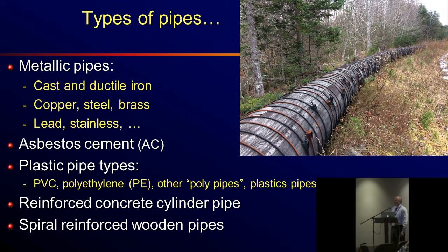Asbestos cement, there's a fair amount of that, as I understand, in South Africa. There's a high percentage of asbestos cement AC pipe. And the beauty of that stuff is that if there is a leak on it, you can hear it. And that's a positive in a sense. That's about the only positive I can think of for AC pipe, but in any event.